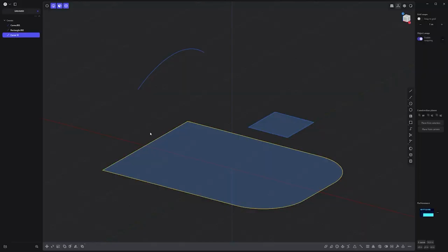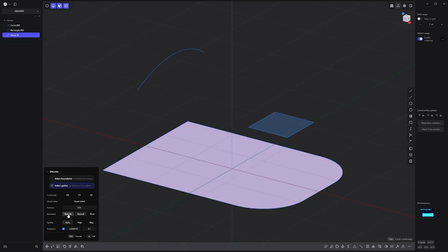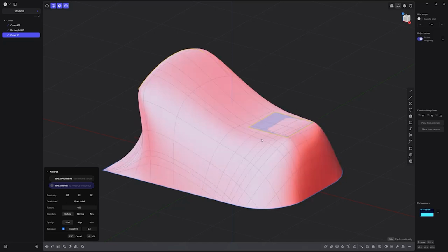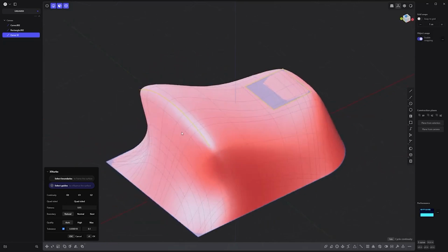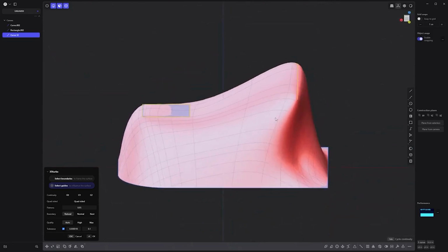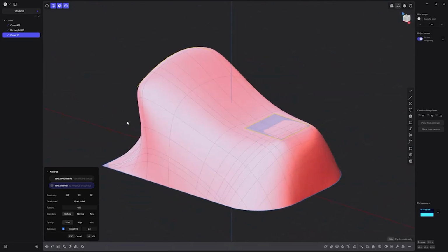When working with XNurbs, you have the option to use guides as internal references. Unlike using guides when lofting, XNurbs guides don't need to touch the boundary curves that frame the surface. This should offer more freedom when using guides to influence the surface. Take advantage of this powerful flexibility when working with XNurbs and plasticity.